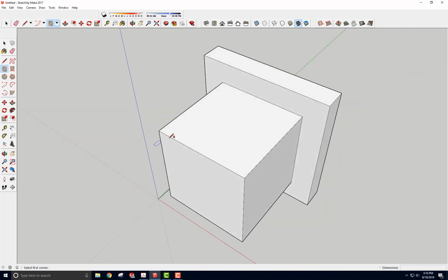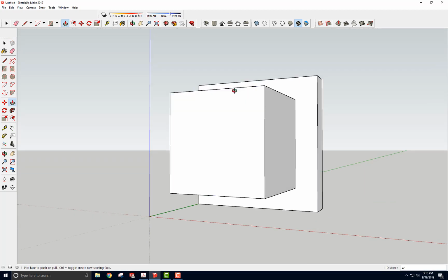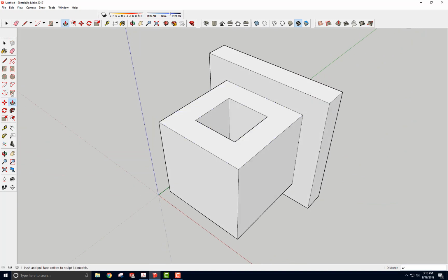And for the top surface, I'm going to click on the surface and create, sorry, not this. I'm going to use the offset again and create a 1 inch offset from the sides, and I'll go ahead and go through this. Rotate around with your scroll button, click on the back surface and cut through. We'll just use the offset button again on this face here and type in a 1, enter for that size. And I'm going to push through and type in a 1, enter to get to there.